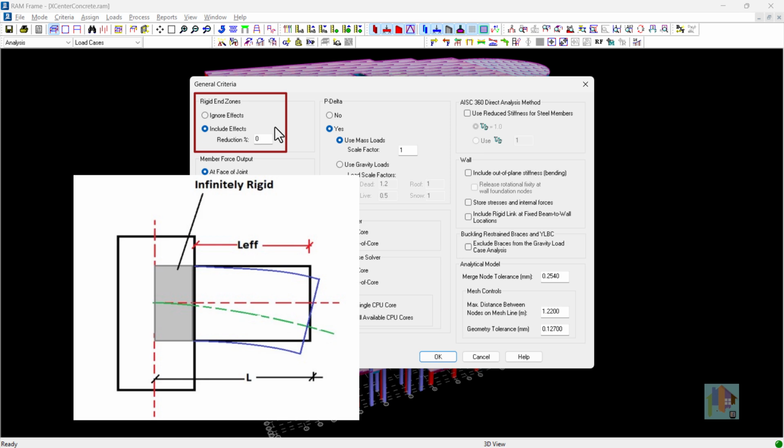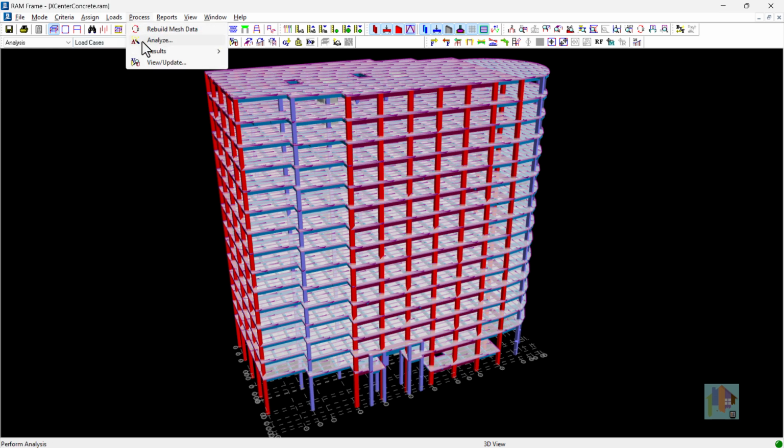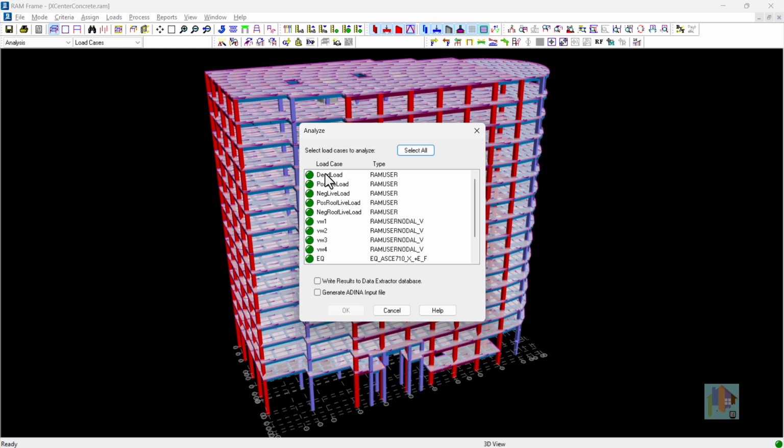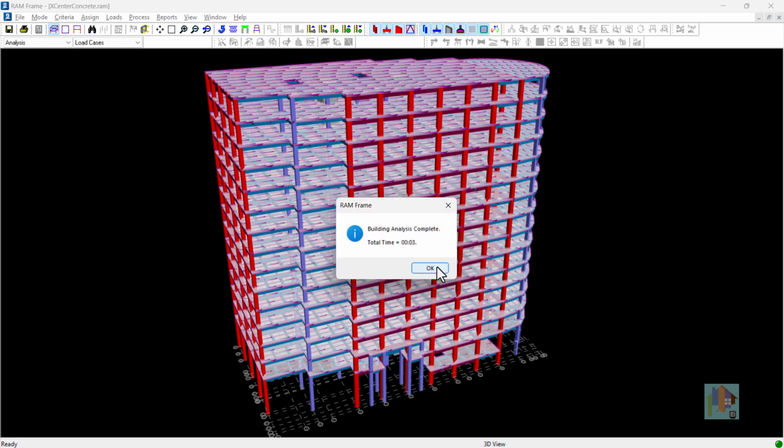High peak moment at the column center is ignored. During analysis, we can select one or multiple load cases. Load case selection is optional. If there is any change in any load case, like the dead load intensity is changed, we can select that modified load only and perform analysis. No need to select all load cases. Result for the rest of the loads will remain constant.